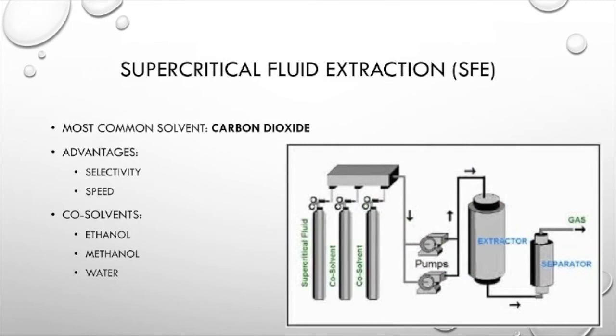The most common solvent used in practice in industry is supercritical CO2. Why CO2? Well, a few reasons. It has low critical pressure and temperature. It is relatively non-toxic. It is non-flammable, and it's easily available to experimenters in pure form, such as in dry ice and pressurized CO2 tanks.